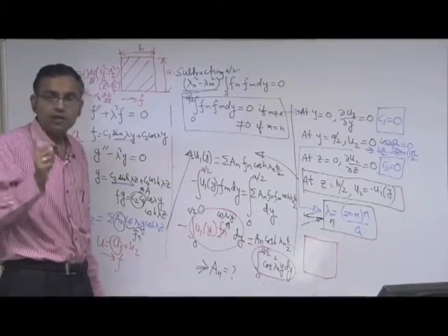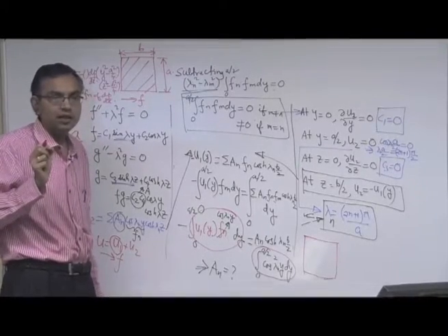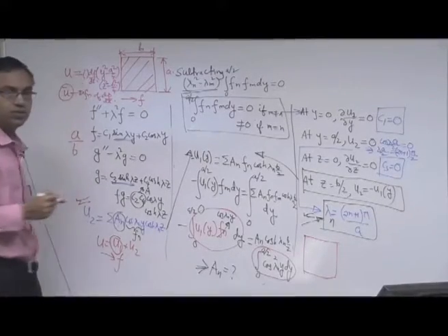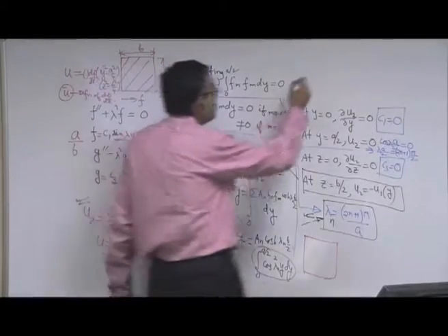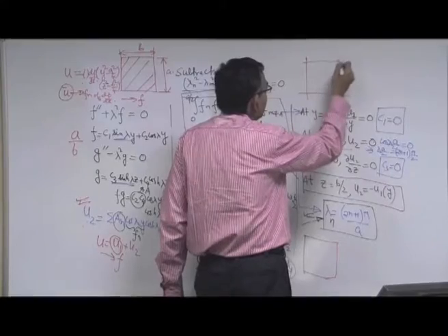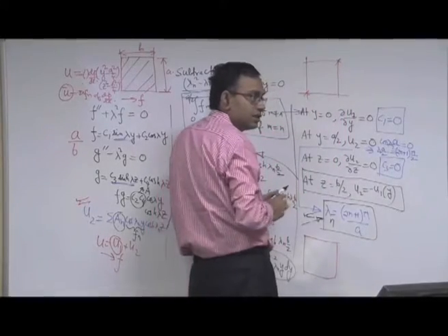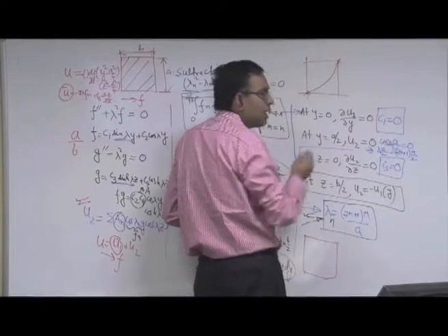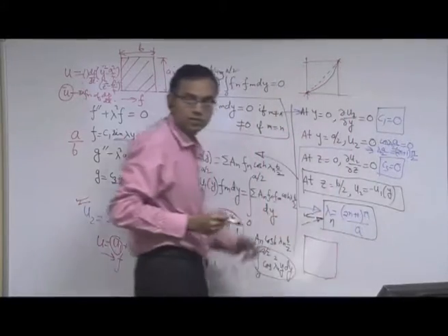One of the reasons is that in calculating the friction factor, you use u average instead of u. See, you have a u between these two limits, you are satisfying the boundary conditions, so this is one boundary condition, this is the other boundary condition. So in one case you have a velocity profile which is very accurate like this, in another case it is not so accurate like this, okay.